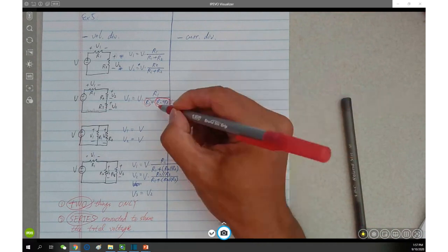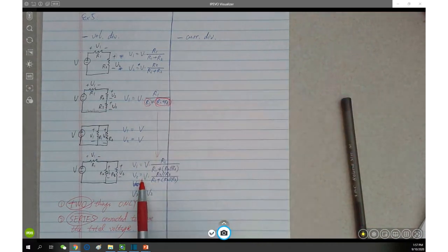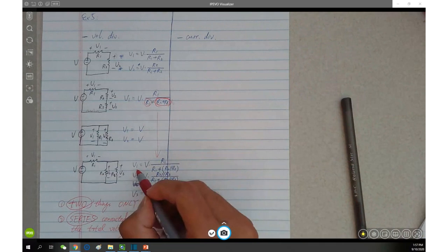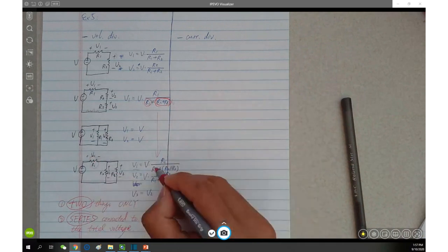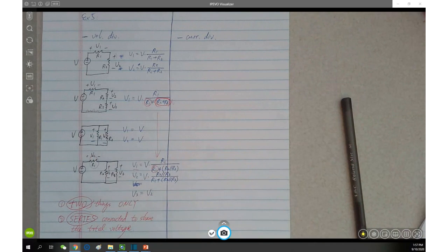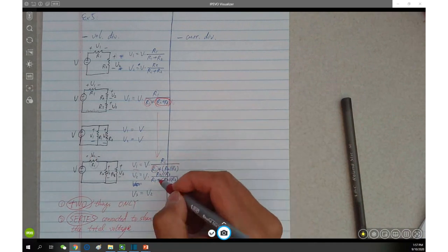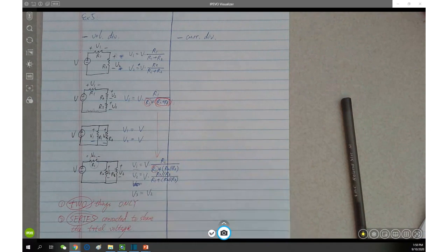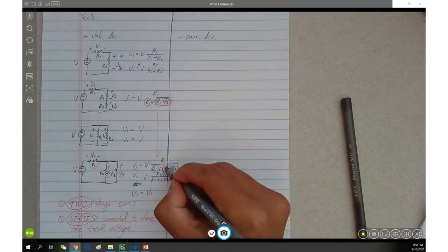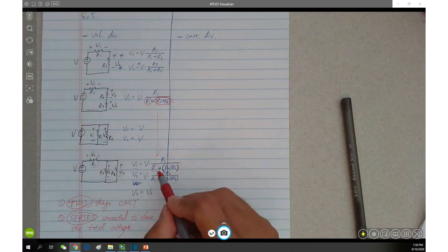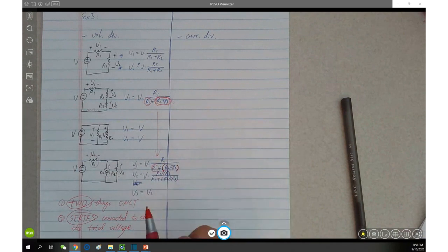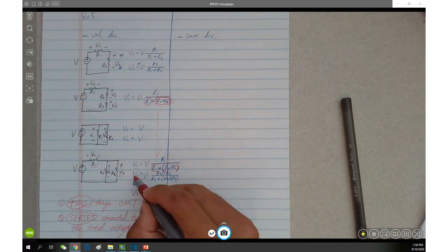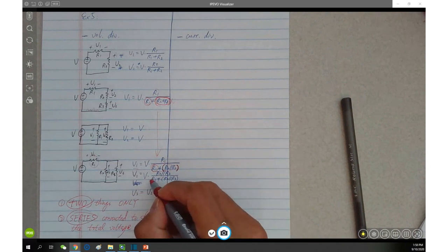Okay, same idea applies onto this V2 and V1. If you're looking for V1, of course, you're going to keep R1 as itself, as one thing. The other thing is you have to, no matter what, combine R2 and R3 together, becomes one thing. You see here? So the denominator is and always is the summation of two things. If more than two things present, what you need to do is to combine. Same idea. V2, how to find V2? Total voltage times the ratio.